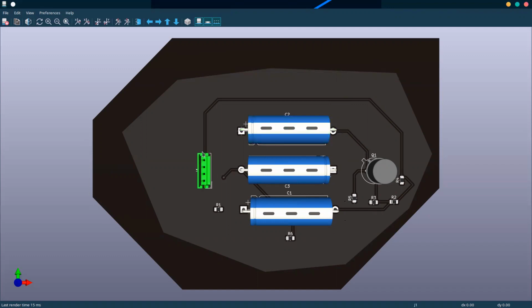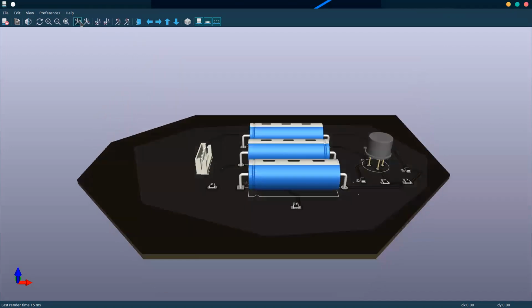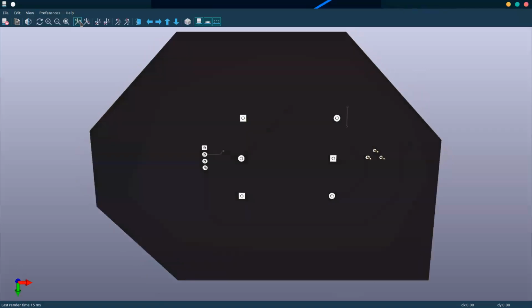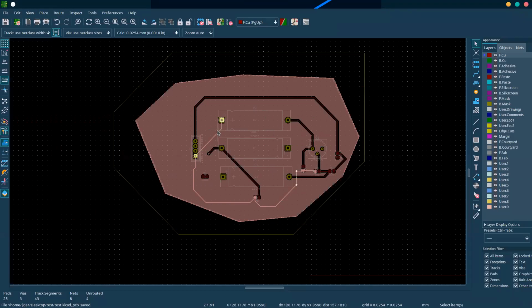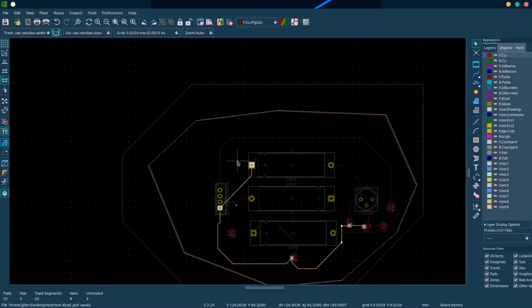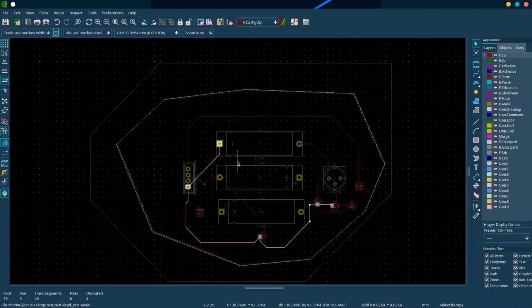So what's going on here is that this trace is still electrically isolated from ground because it's got this little buffer zone around it, but everywhere else here is all ground. And the reason you'd want to do that is it helps reduce interference, because ground is kind of like blocking electromagnetic interference, basically. There's other reasons to do it too. So you can use it as a heat sink as well, if you want. It's pretty common to use it as a large heat sink in some cases.